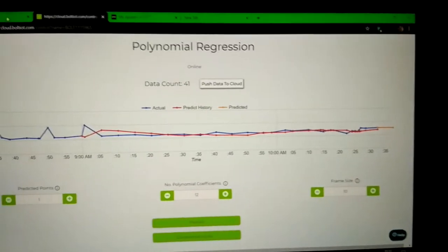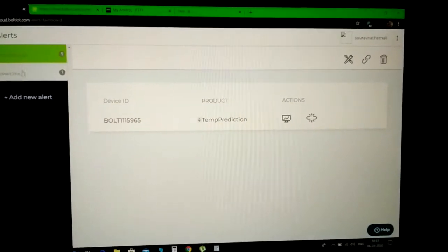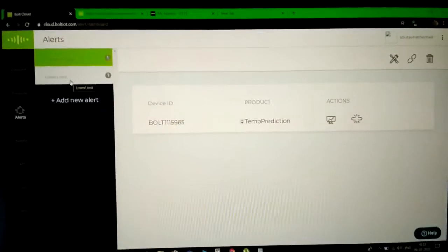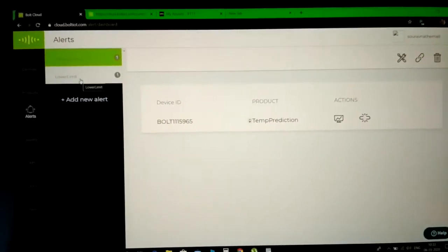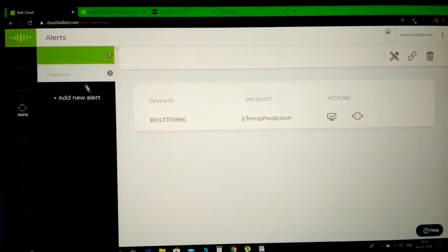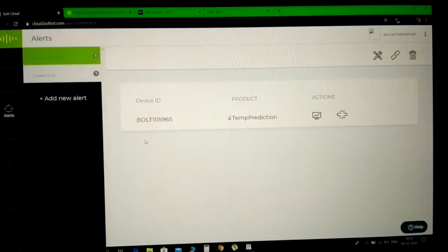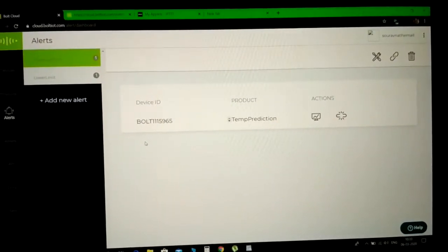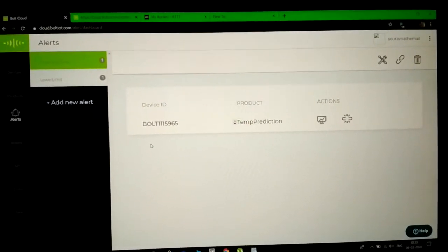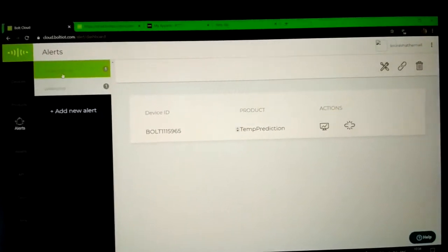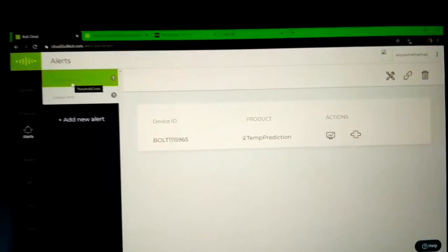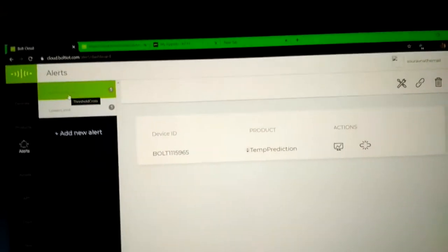For the alert system, I have used an idea in such a way that if it crosses a particular sensor value, which I have given for both the alert systems as 275, which roughly translates to 26.86 after multiplying it with a multiplication factor of 0.0977, and if it crosses the 26.86 limit, then I get the higher temperature alert, which I have already got.